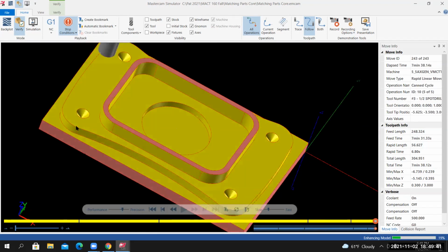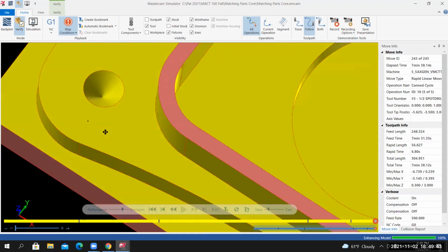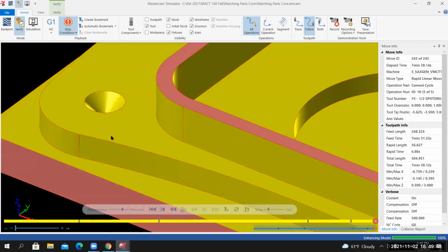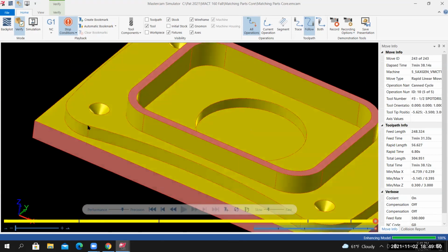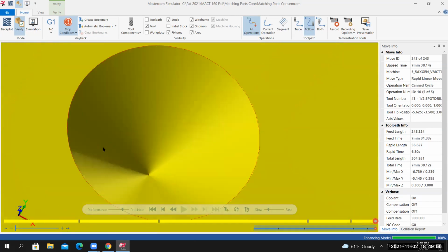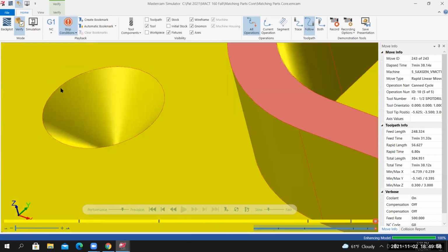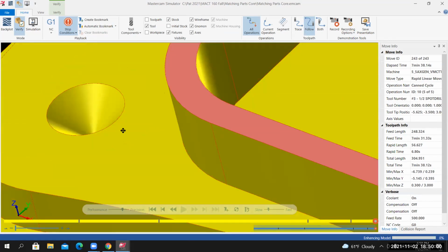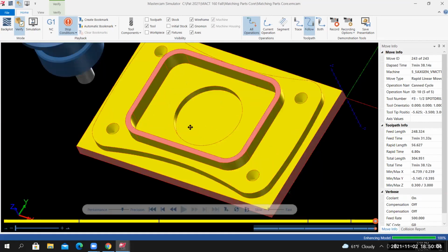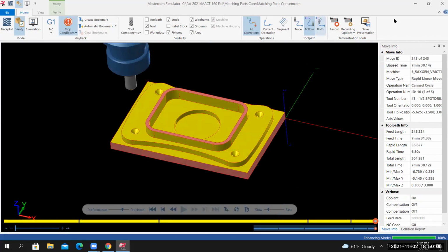Once verify is done running, once again, I'm inspecting the machined model against the wireframe representation of the part. And in this case, you can see that the diameter of the pilot matches the diameter of the circle that represents the hole. And that's what we're shooting for. That's what we want. So that looks good. From here, I'll exit out of verify.